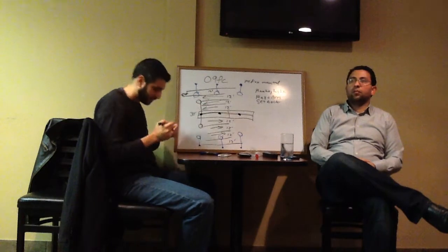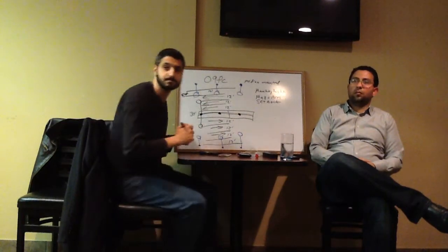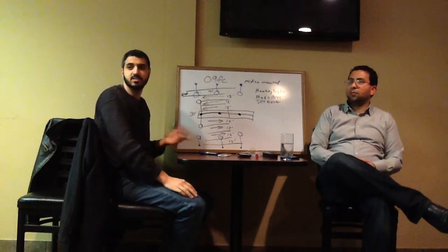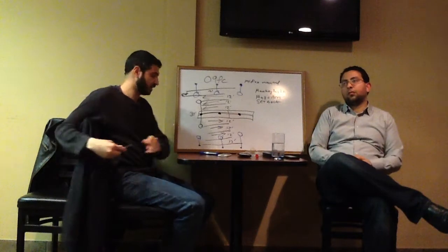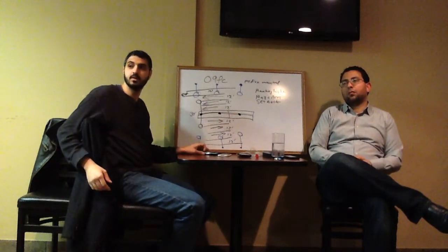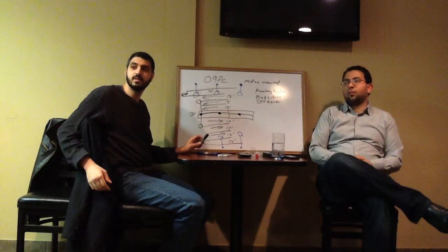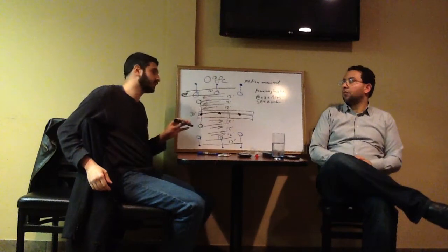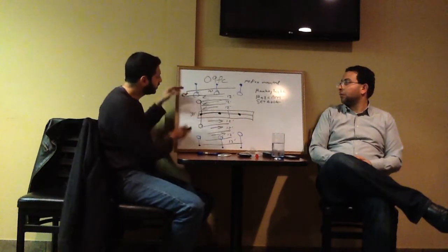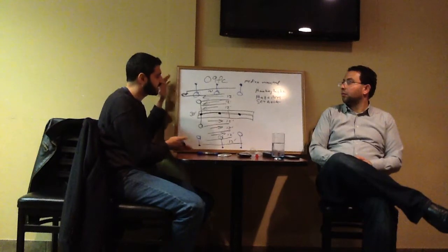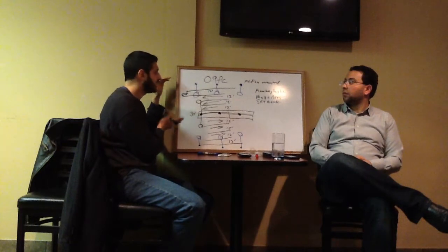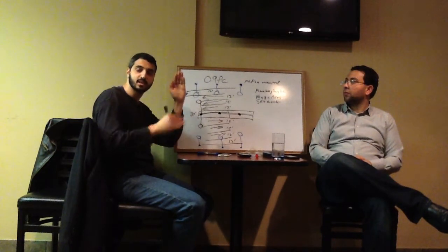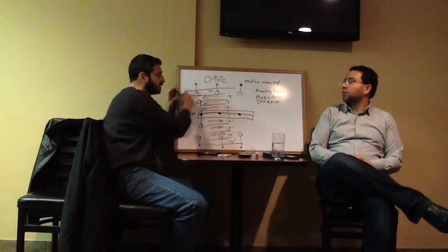Do they, in this case, up-tilt the fixture sometimes? Ideally I would have it on top of the street, but because of safety issues I don't want it to fall on somebody. So to compensate, do they do some kind of tilting? The tilting we do only if the photometrics require it, for example a really wide roadway, like 6 or 7 lanes, where it's very difficult to adequately light that roadway. Then we sometimes tilt the light so that it throws more light forward, and we don't worry about the light that falls back here.